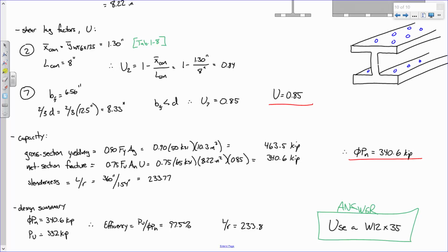That bridge would be classified as what's called a fracture critical bridge. So, anybody remember what happened on December 15th, 1967? Silver Bridge collapsed. When the Silver Bridge collapsed, the reason it collapsed is because a single load-carrying member failed and it caused the collapse of the entire structure. That phenomenon is what's called fracture criticality, the idea that if one member pops, the whole thing comes down.